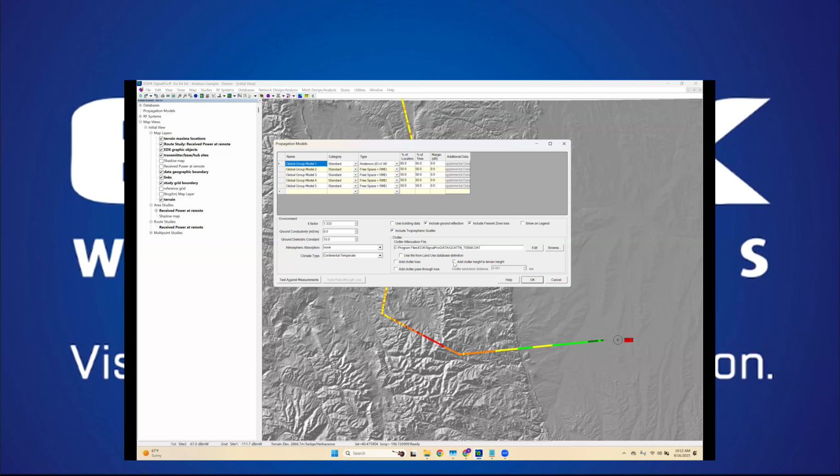Potentially, if we want to, we can include clutter screening for the height if it's sitting along a ridge or something like that. But more importantly, we may want to build additional variability losses onto the model, and we'll want to be pretty strict with those variability losses. You'll notice in this case, I've used an Anderson 2D propagation model, which is typically the choice, an Anderson 2D or potentially the TIREM.